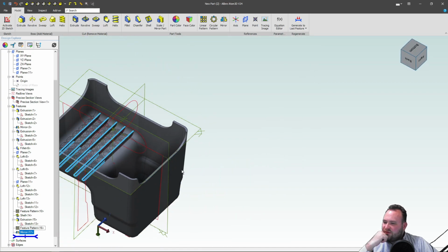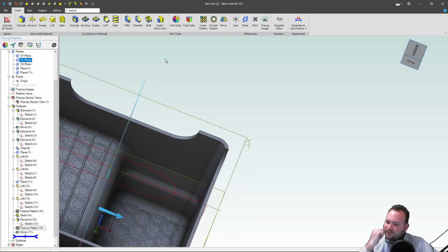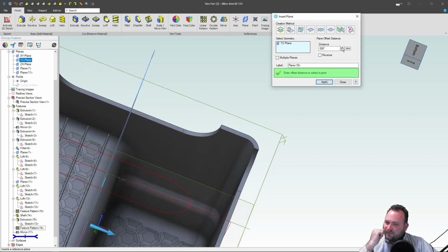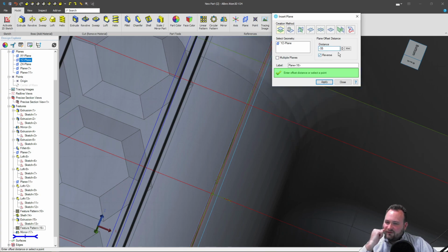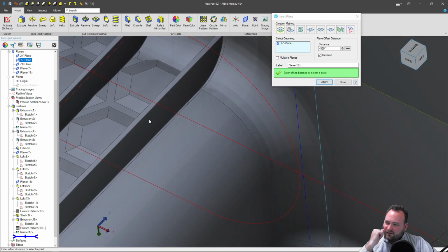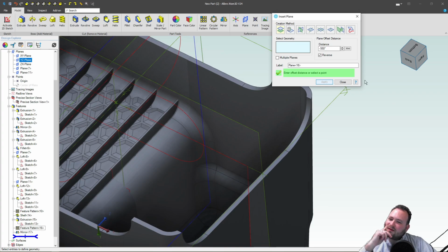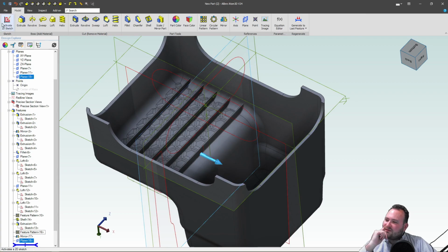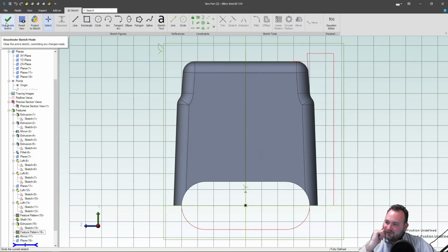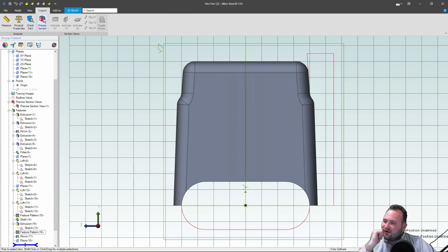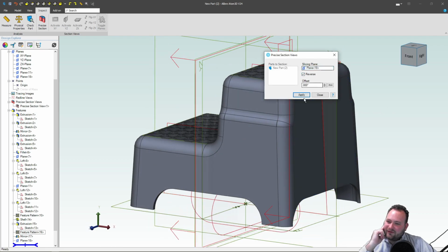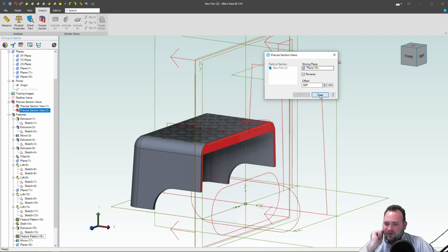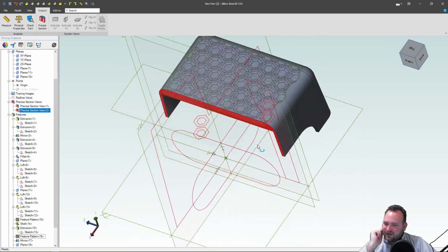Next, let's go with this plane. And we're going to create a plane referencing off of that. And we're getting pretty close. Let's say negative 0.55. Yeah, we're kind of on the far end of that rib. I like that. So negative 0.55. Close that. Highlight our plane. Activate a sketch. Now, of course, I can't see anything that's meaningful, so we'll go to Inspect, Precise Section, rather. And it looks like plane 18 is pre-selected. We'll reverse our view. And close, right? So now I'm looking at the rib, which I think is a little bit more useful.